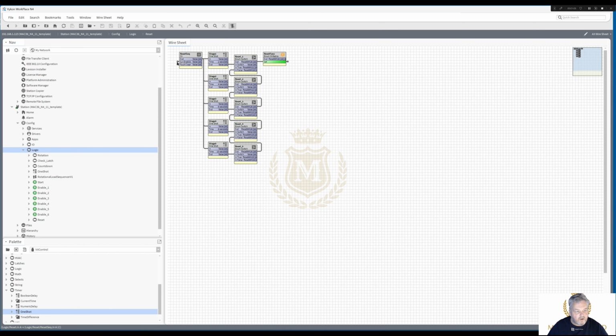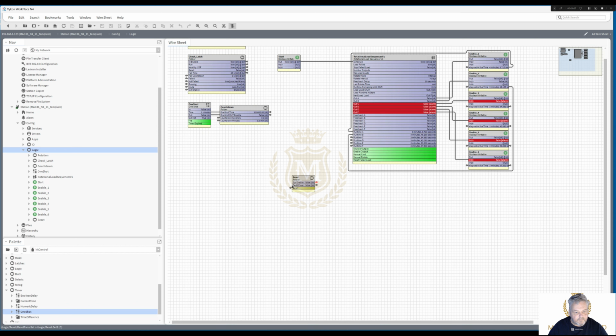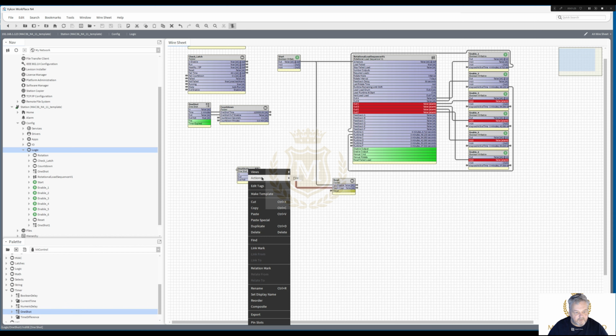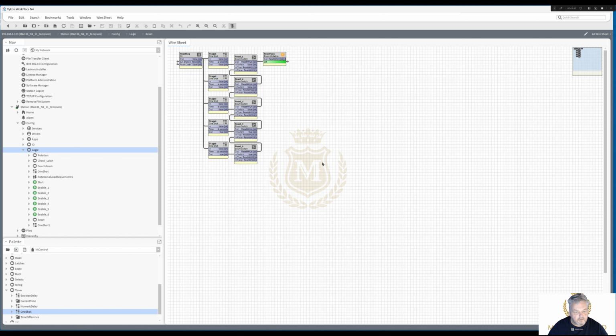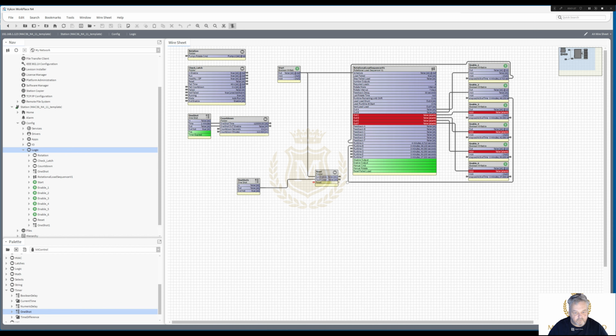So we've got coming in system enable. So once the system is enabled, it sends a reset, and then of course you can use a one-shot timer. Let's just put a one-shot across here and take the output into the fault clear, fire that, and that will send a reset. Naturally I've not linked it up yet, but that will send this reset here, and it's going through resetting everything. Let me just put that into there.